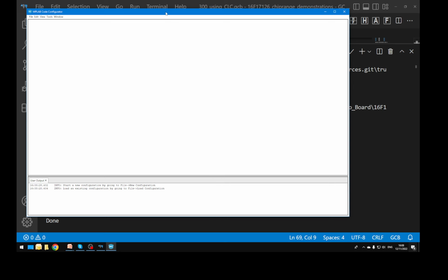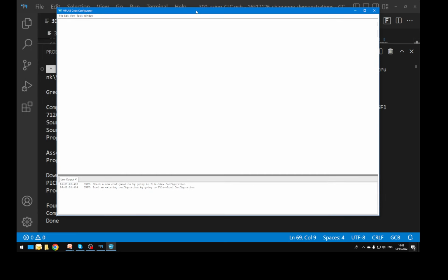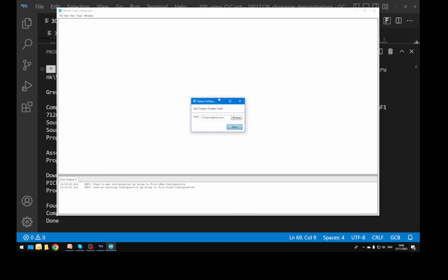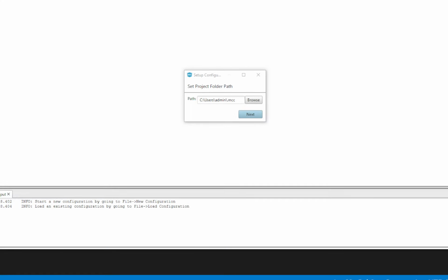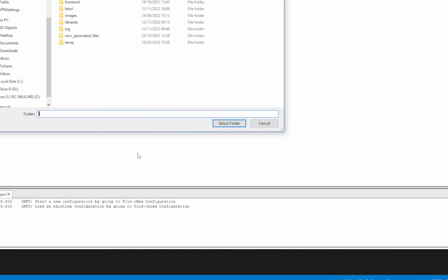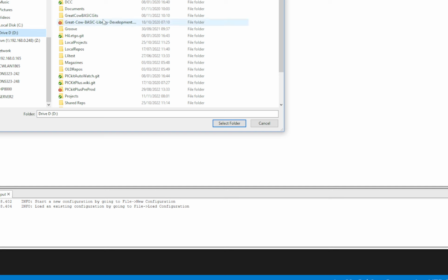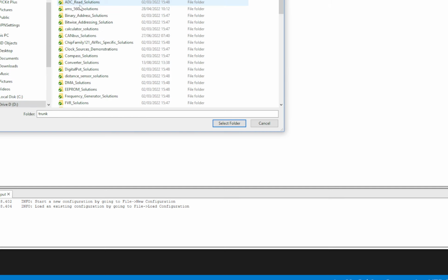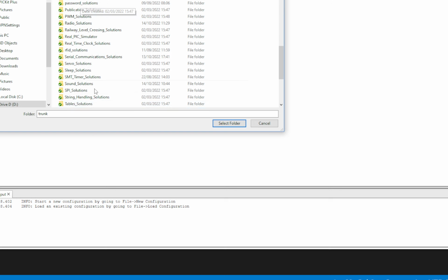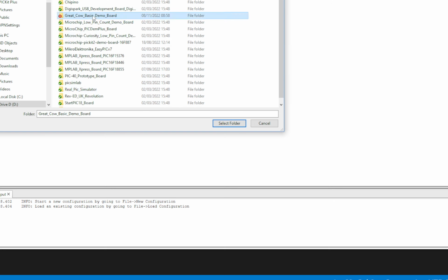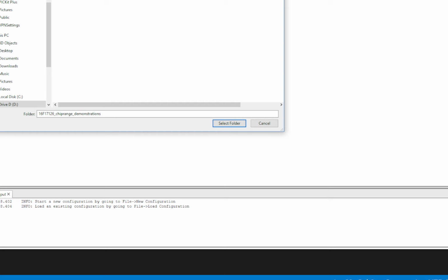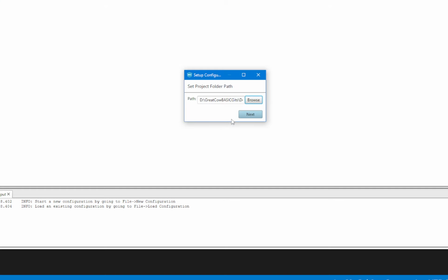There is a tool that you can download called MPLAB code configurator. And I'm going to create a program. I'll zoom in on what we can see. You'd ask for a project name. I always put it in my folder where I'm working because I might want to come back to it. So I'm going to come into my vendor boards where I've got my project sitting, and I'm going to call it new folder. I'm going to call it CLC. I'm going to select that as my folder.